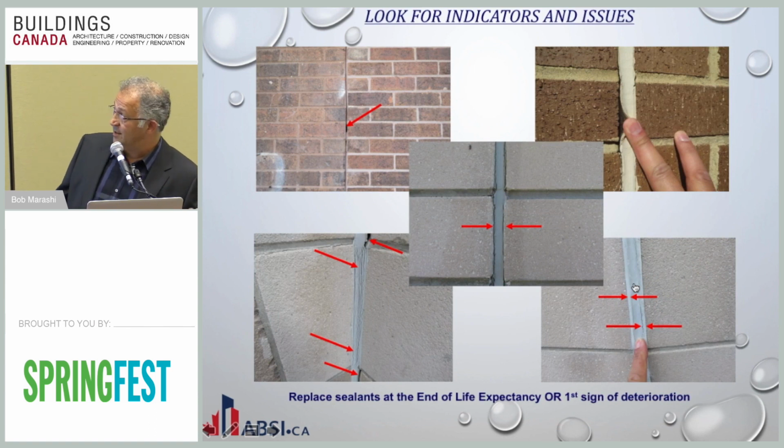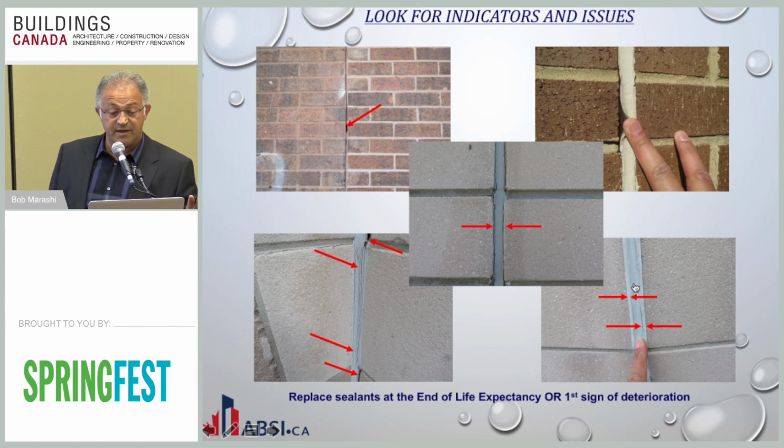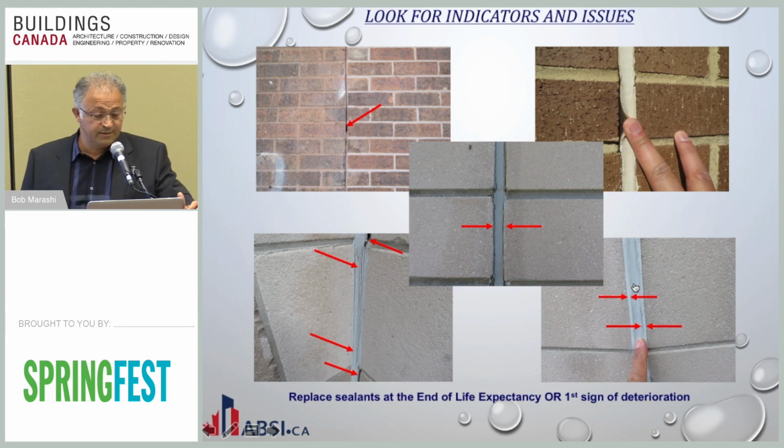When you apply a sealant, it has to actually stick to something. This shows a fresh sealant. It's fresh. I mean, it's still flexible. You can bend it, right? But it's not attached to anything. It has to be continuous with no holes in it, and it has to be attached to the surfaces that it's applied to, not like that.